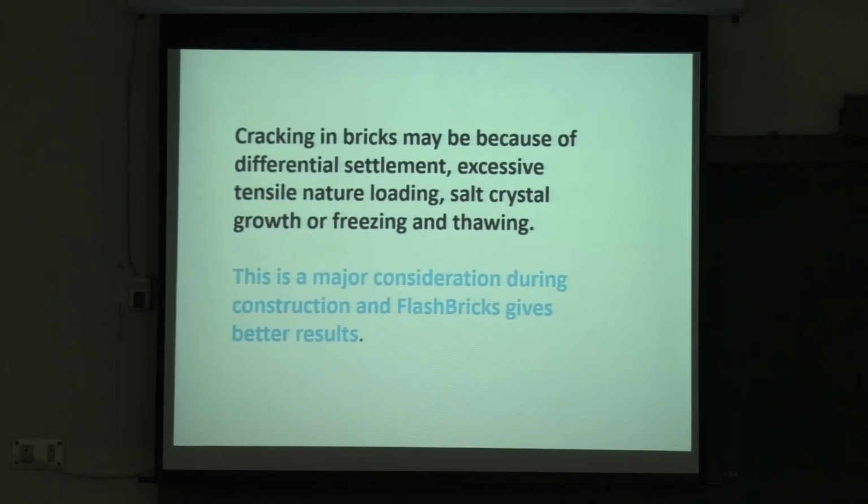That's why often you will find that there are cracks in the lower part of the bricks, because it cannot take it. Even the hostel where we are staying, when you go up, I can see near the bottom of the staircase, not the bricks, but in the concrete structure, there is more cracking because the load there is so high.